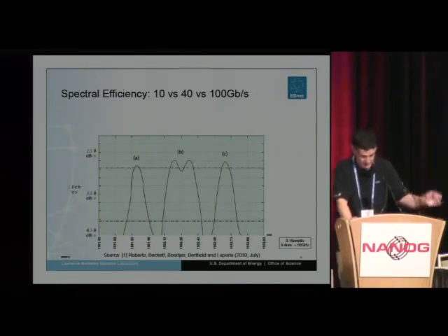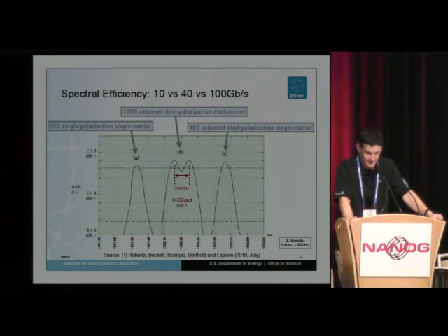So here's an example of what this looks like from a spectrum perspective. In the middle, there's a 100 gig signal. This is basically 2 carriers spaced 20 gigahertz apart, with each carrier running at about 14 gigabaud. So what we basically have here are 2 carriers, we have 2 polarizations, and we have 2 bits per symbol from those constellation diagrams we just looked at. So what we end up with is these 2 14 gigabaud carriers turning into a 112 gigabit per second signal.